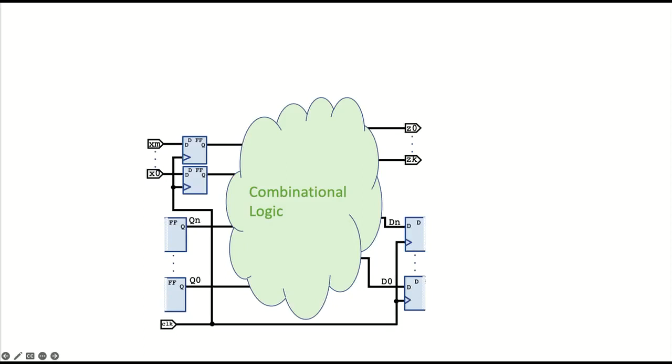Try to simulate the whole thing together. It's a good idea to maybe just simulate your state machine by itself once or twice, but you're controlling all the inputs, and you aren't reality. Once you get a certain degree of confidence in your state machine, simulate the whole top level together, because then you have the counters and the LEDs interacting with your state machine.